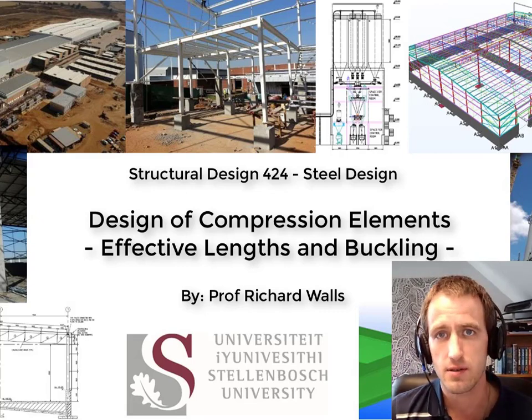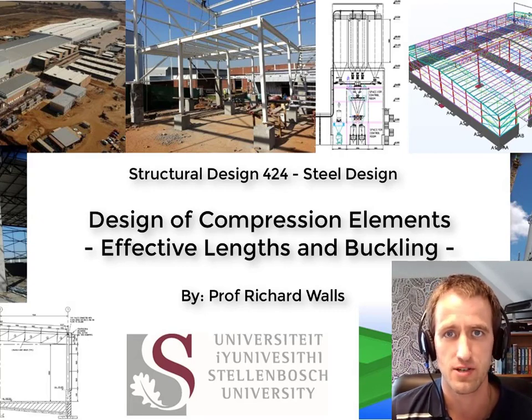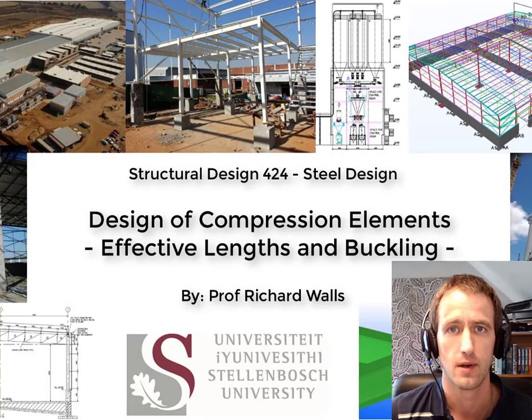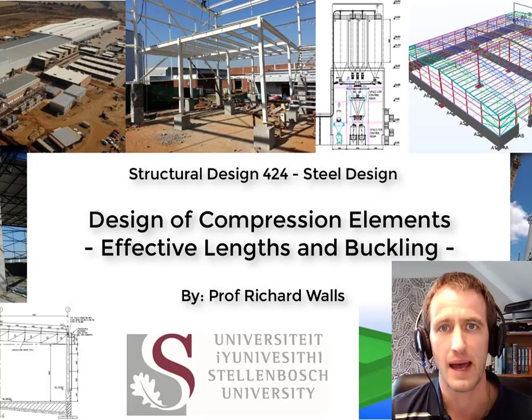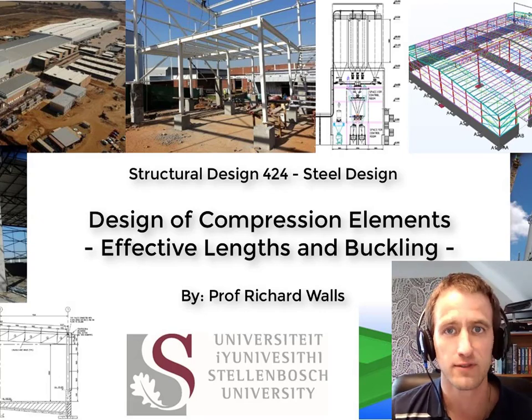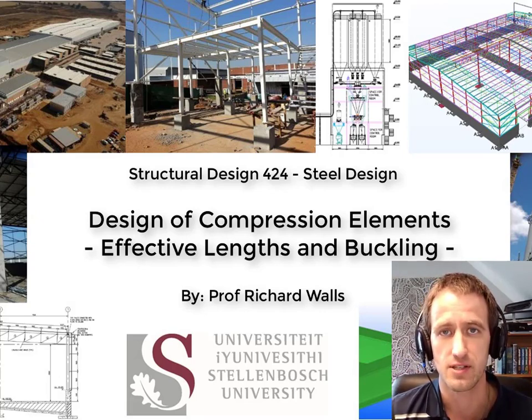And if you get something like a class 4 classification or effective area wrong, it's not going to kill anyone. It's not going to cause your building to be badly under or over designed. You might be 5 or 10% out. But if you get your effective lengths wrong, you may have either half or double the predicted capacity. So this is a truly major issue in terms of real-world design.